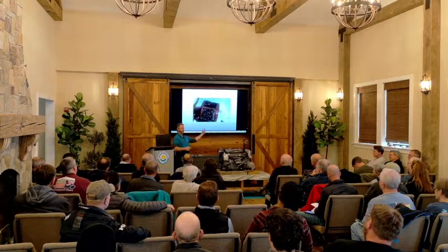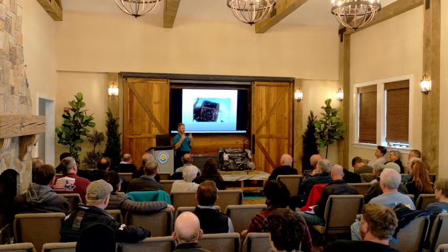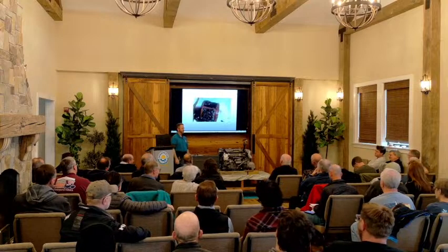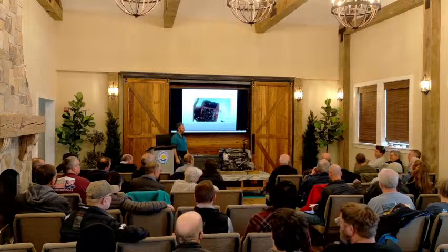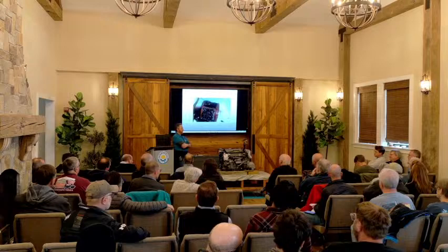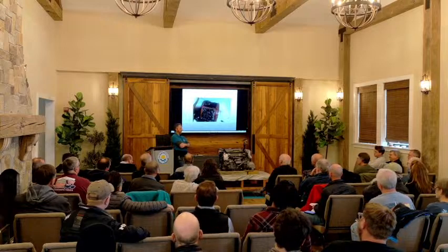Yeah, so I'll run the fuel line directly to the Racor, and then from the Racor to the electric pump, and then to the engine. That is an important point. The Racors are meant to be operated upstream of the pump. Right, they're supposed to be under a vacuum.